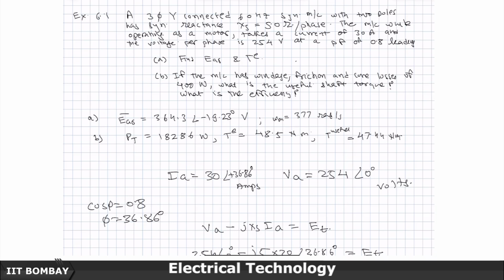Why do we say core losses? Core losses because the AC winding is having alternating flux. Alternating flux will create hysteresis and eddy current losses. So, you need to laminate the stator winding also, and there is no problem in laminating because it is not rotating anyway. So, core losses will be there. Friction, because anything when it is rotating will create friction, so friction has to be overcome. Windage is because it is rotating in air. So, the higher the speed you rotate, there is some windage loss. Windage is not coming from winding, windage loss is coming from the word wind.